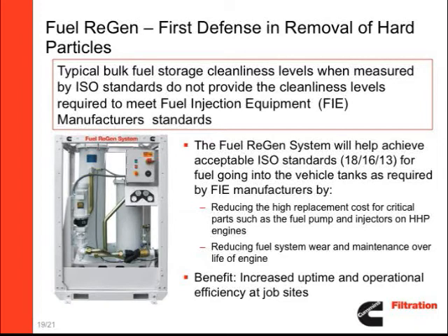The FuelRegen system helps achieve an acceptable 18/16/13 ISO standard as required by fuel manufacturers, thus reducing the high replacement cost for critical parts such as the fuel pump and injectors on HHP engines, and reducing fuel system wear and maintenance over the life of the engine. Adding the FuelRegen system to a bulk fuel storage tank will result in increased uptime and operational efficiency at job sites.